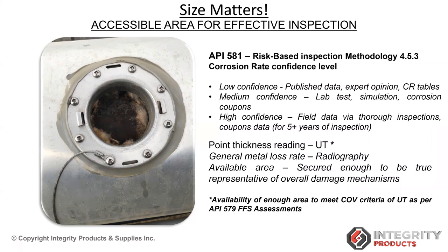I can give you an example, like API 579, a standard meant for FFS, fitness for service assessment of pressure vessels and piping systems. The challenge being addressed from the CML point of view is a factor called coefficient of variance. For example, if we are taking the ultrasonic thickness at a pipe and it's too small, we can get only one reading. One reading could be underrated or exaggerated. It could be anything. For sure, and you want to use that inspection point to represent the rest of the line.